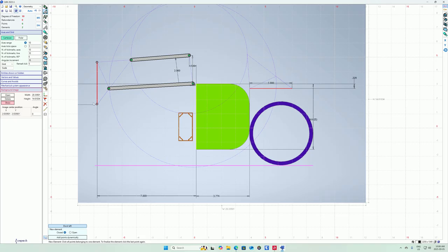Now I need to create this frame here. And you'll see when I do this that all these merge together, which isn't a problem because you'll just define some revolute joints. But the first time I did it, it kind of threw me for a loop. So I've created my frame. It's attached everything together. I click again, and it created the element, and you notice it merged everything together like I said it would.